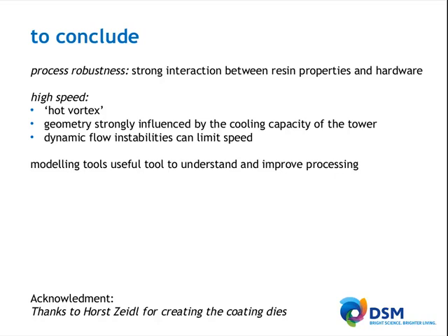Next, do differences in CTE between primary and secondary contribute to coating defects? So differences in CTE, I would expect them to be expressed in a later stage. What I really talked about here was purely about processing instabilities, which I know are initiated inside the coating die. If there are differences in CTE, you would expect that you generate residual stresses inside your coating geometry, and they should pop up at a later stage, so when it's on the reel.